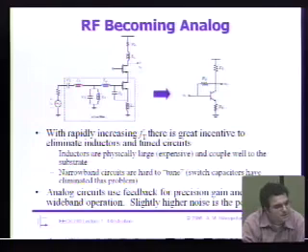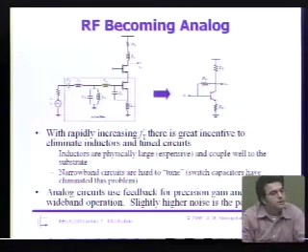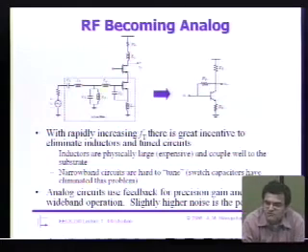What's the advantage of this analog? Compare left and right. What do you have a lot more of on the right-hand circuit than you do on the left-hand circuit? Feedback. That's right. Analog circuits use feedback, and feedback is really good because it makes the circuit performance essentially a function of your feedback network. So as the process varies, as long as the ratios of the resistors track fairly well, this amplifier's performance is going to track fairly well.